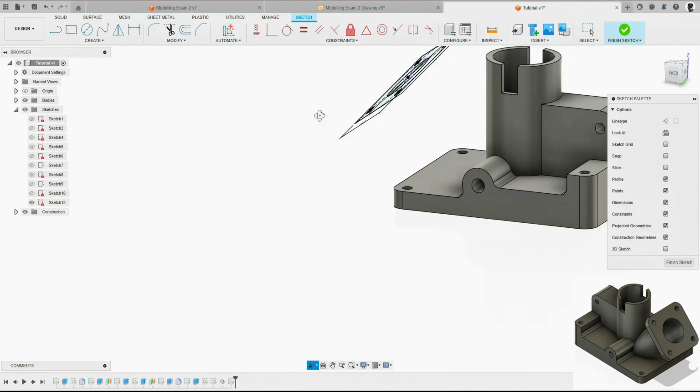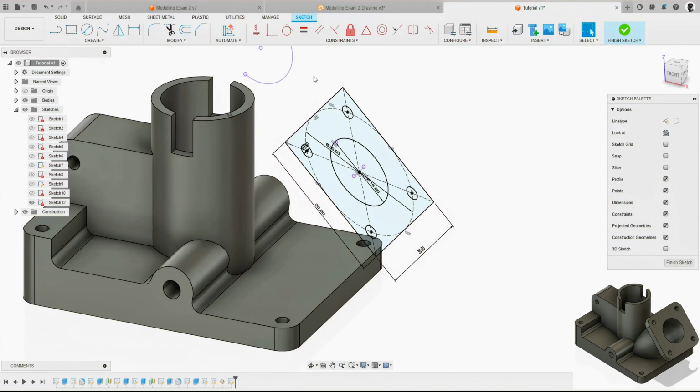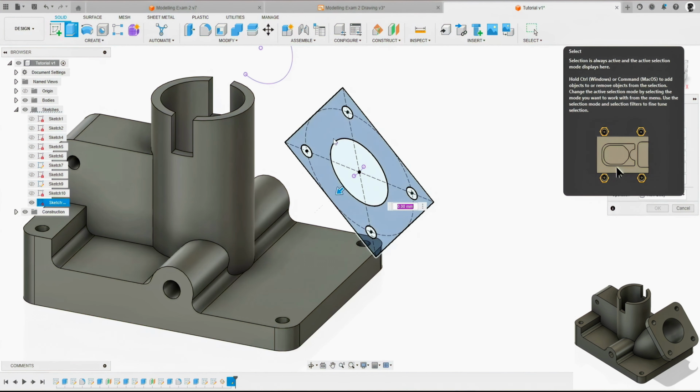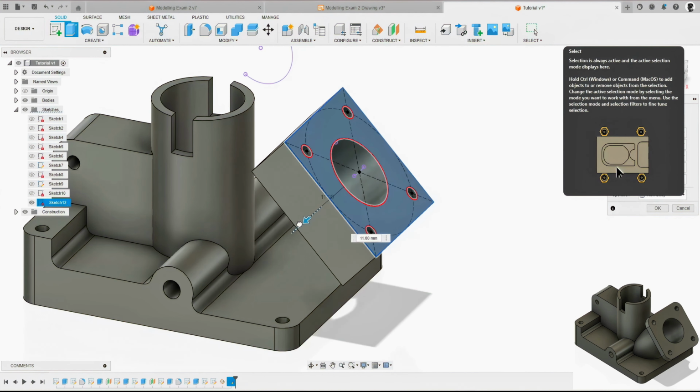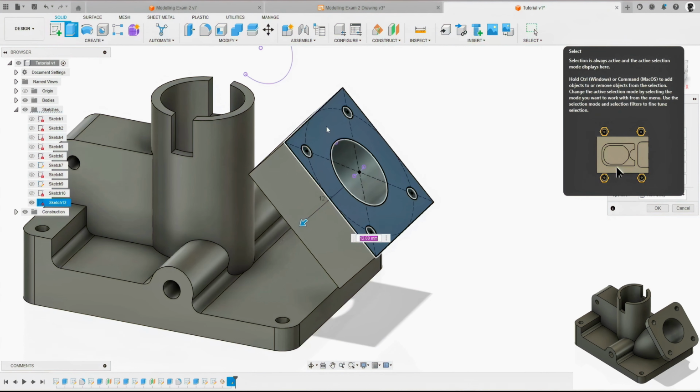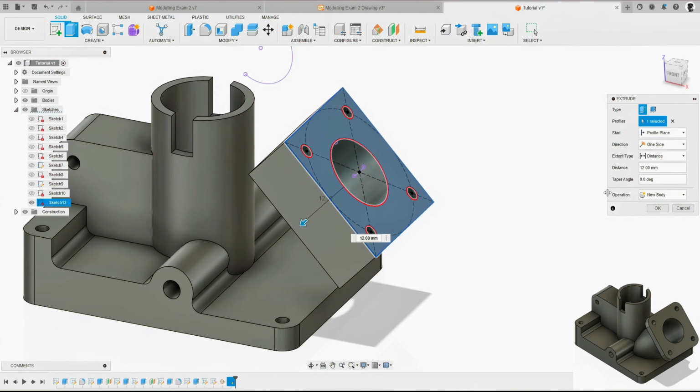All right, I think we're almost there, ready to extrude. Let's finish that sketch then. E on the keyboard, select our profile. Also make sure that we're extruding in this direction, not in this direction. Okay, because when we put on our construction plane, it was this face of the flange. And so the distance, or thickness rather, of the flange, we've got 4 mil.